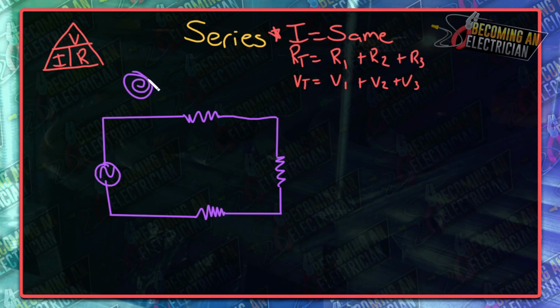These are purely resistive. And so what that means is we can apply Ohm's law directly. And also with Ohm's law here, we also have our power triangles, okay? So this would be P, I, and then V. And again, the same stuff applies. Like if you're wanting to find voltage, then you're going to go power divided by current.